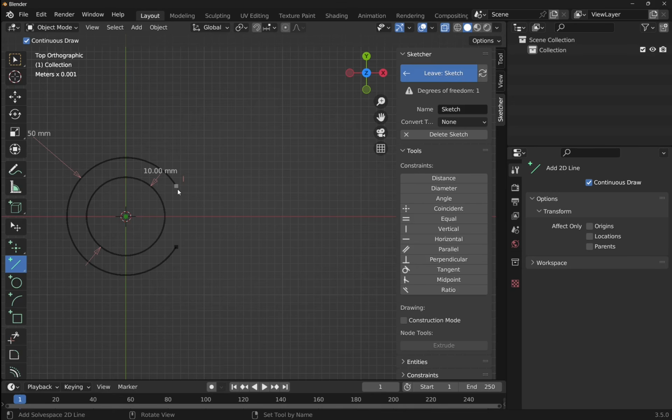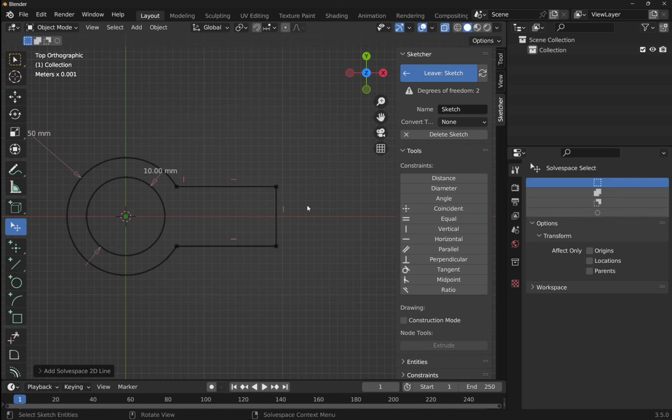Starting point is this point. Hover over it, we get coincident. Once we click, the line comes out, drop the line, bring this down, click again, and then finish by clicking, and we get that in place there. Right click to cancel the tool, and that sets some length in here.